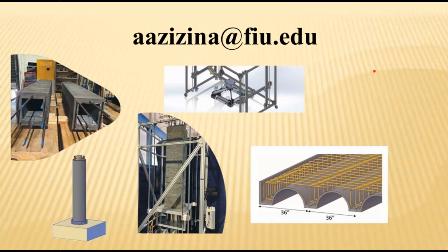So what was the advantage, do you think, of doing that one versus the other direction? In this one, the gravity helps the concrete to get consolidated, and we found out that that's very helpful. So if I come from the top, it was more stable. We did the other way too. We had another printer that was going from the bottom up, but top to bottom was very nice.